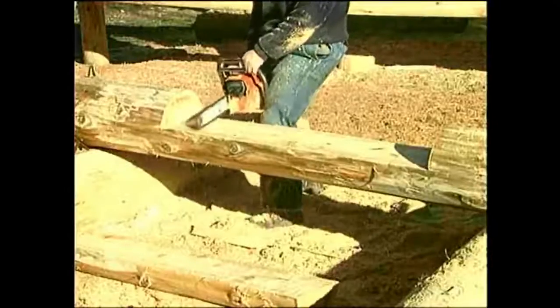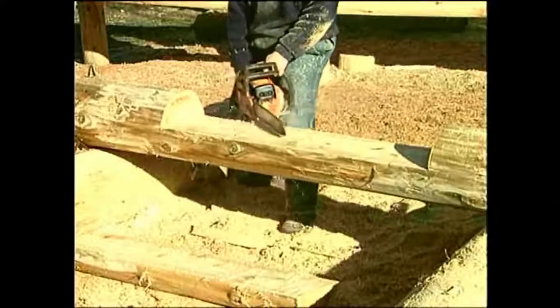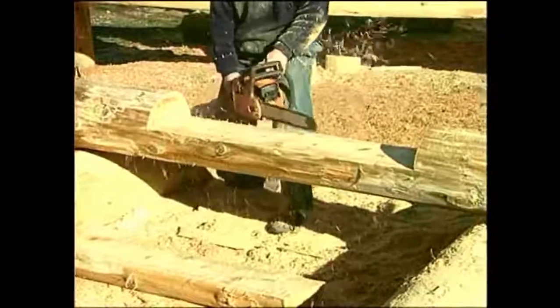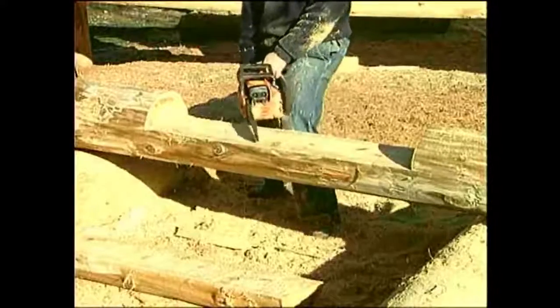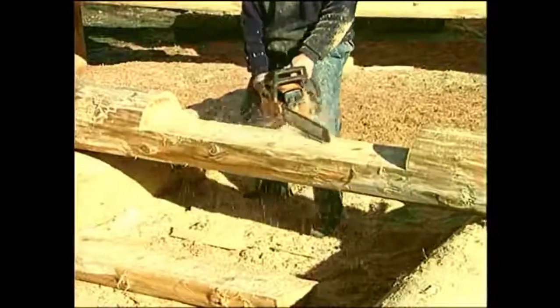Brush the flat down to the line, then lay out the end cuts for the keyway and the window trim. It is very important to make these cuts in the window header at this point in the building. If they are postponed until the wall is complete and on the foundation, they will become a very dangerous and time-consuming undertaking.